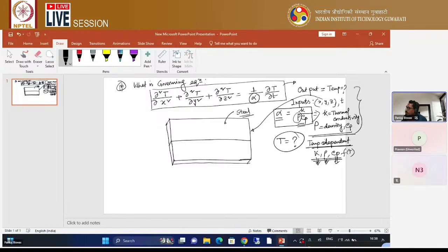That's why for doing the analysis, you need to consider temperature dependent material properties. If you use temperature dependent material properties, then the transient thermal result you get will be like this, just one transient thermal profile I am drawing. This is your time, this is your temperature.